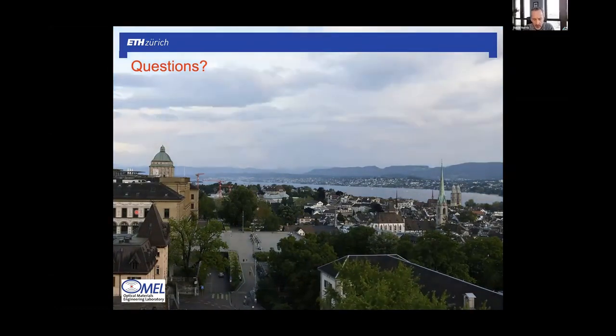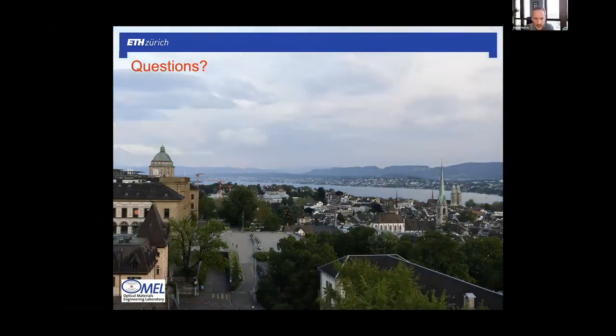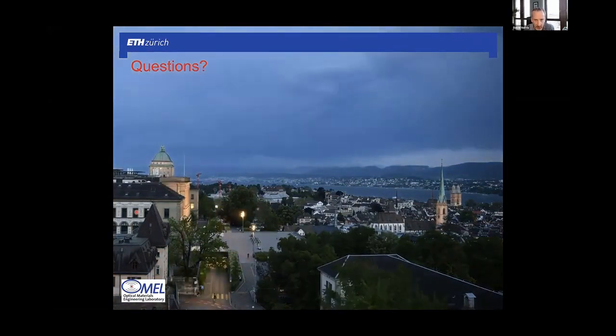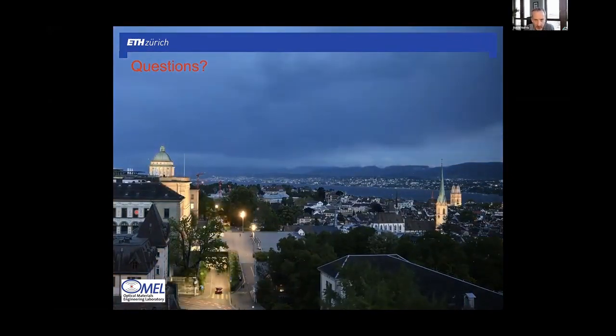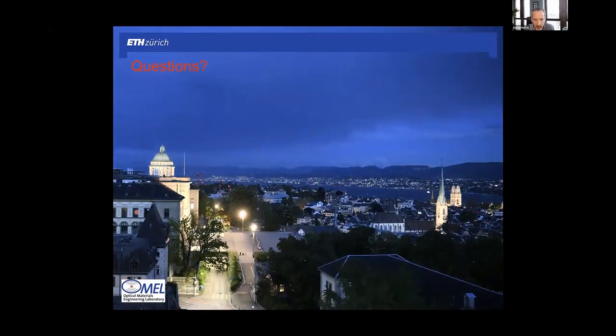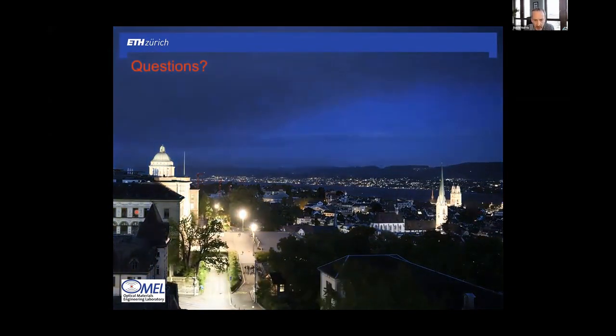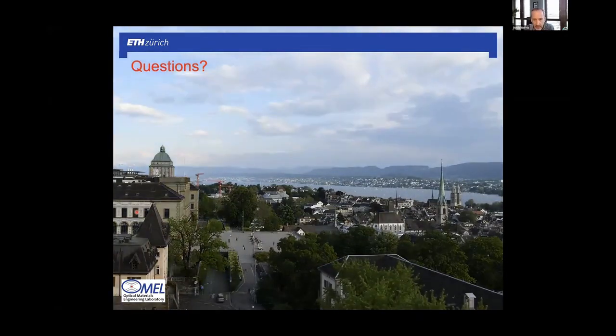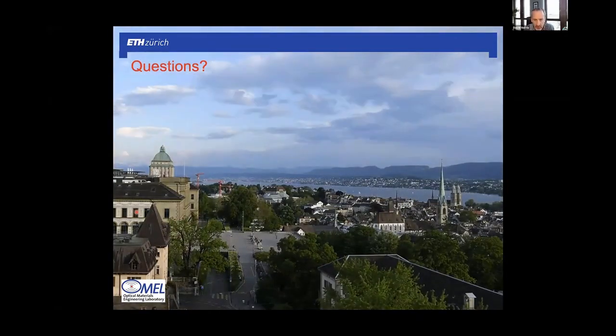So typically we just want our films to be optically opaque. And so in the case of silver, we usually deposit 250 nanometers-ish or something like this. It could be thicker, it could be a little bit thinner, but this is just the ballpark. For the use of template stripping for making other dielectric structures or whatever, then we use this thin layer of gold.